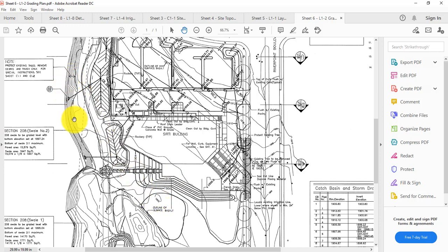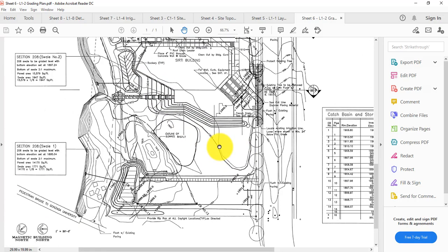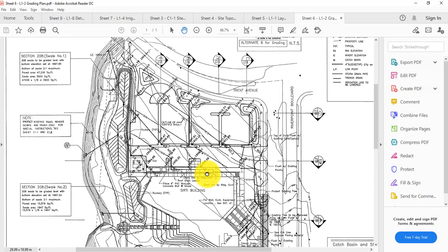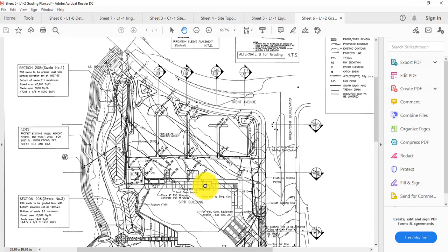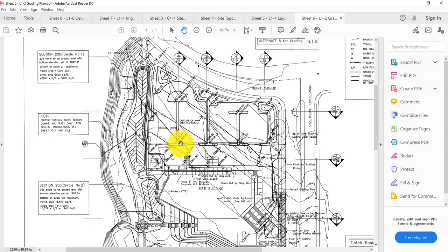And then we said that contour lines that are close together are going to be steep. So the ground over here by the river is pretty steep compared to the ground over here that's opened up a little bit more. Okay, you can see there's your CB for catch basins, and let's see, I'm thinking about all the questions that are asked there. Spot elevations. Here's catch basin number 5. That's one of the questions there. Catch basin number 5. It drains over towards these rocks here.